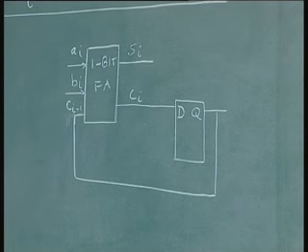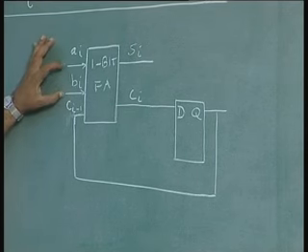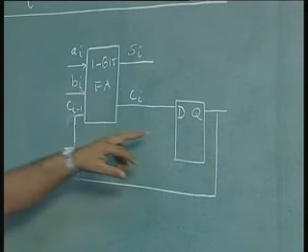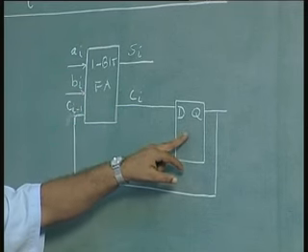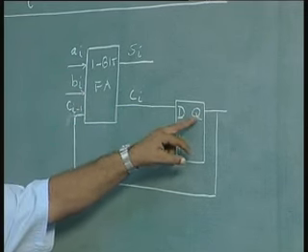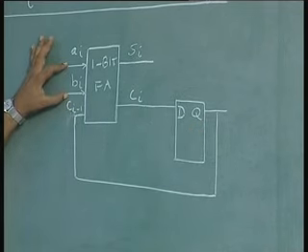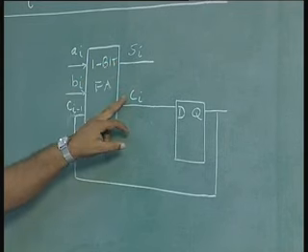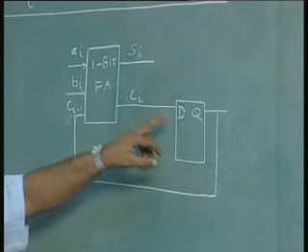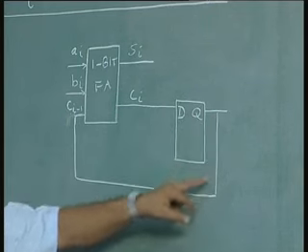Now, as each bit is placed here, first of course we will have to reset the flip flop so that the flip flop Q will be 0, so there is no Ci minus 1. So, first 2 bits come, get added, there may or may not be a carry that gets stored here, and that becomes the Ci minus 1.